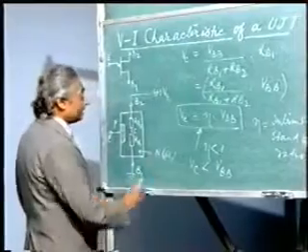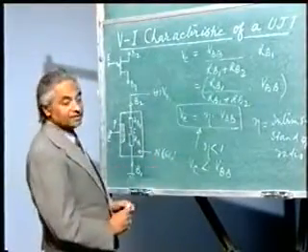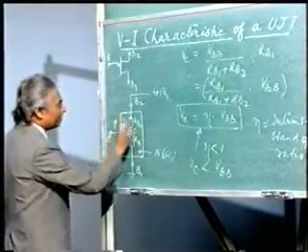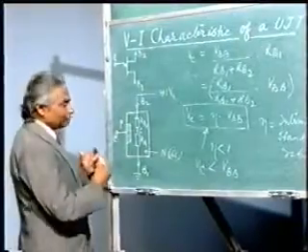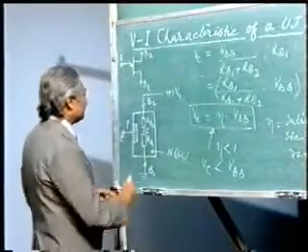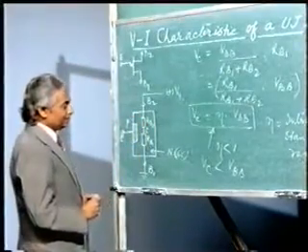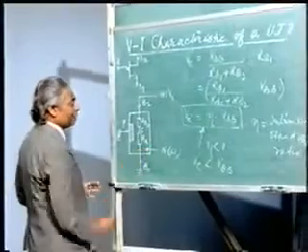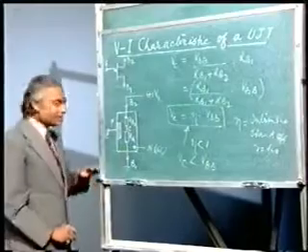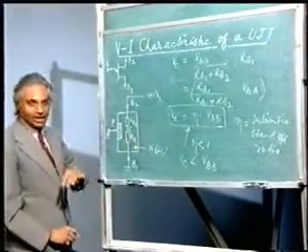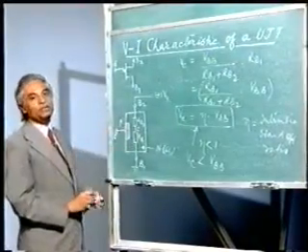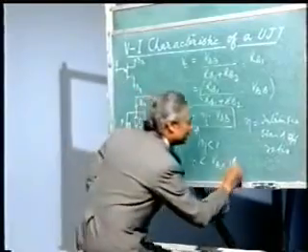Now the two things on which this depends apart from VBB are the spacing of this terminal emitter between B2 and B1. Where is its space? That is very important. It will depend on that. And the second thing it depends on is the construction of the device. Now if I replace this N material by P material, suppose here we have the N type of base. Suppose I replace this N type by a P type material and I diffuse N material in place of P, the same device will become a complementary UJT.